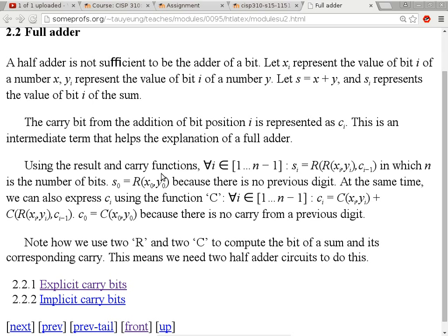This one is going to be done just like that because this one does not depend on anything else. It only depends on the two bits of the numbers that serve as the input. This guy, on the other hand, depends on the input carry, and that can have a long delay because it depends on how many bits are before this particular full adder. But until this guy is done, the output of this OR gate is unreliable because it's not the actual finished product. Oh, but there will be an output, but it's not reliable.